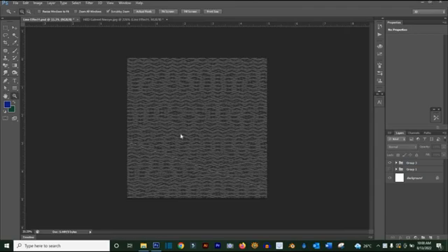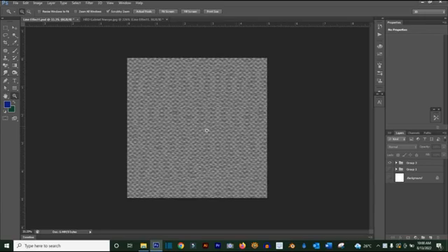We are now going to go into making use of it. So what we're going to do next is to save. We are going to save it as a PNG. For you to save as a PNG, you see the background here is white, so you have to hide this by clicking on this eye icon that indicates layer visibility. You click on it. Okay, you see it's off. The white background is out.